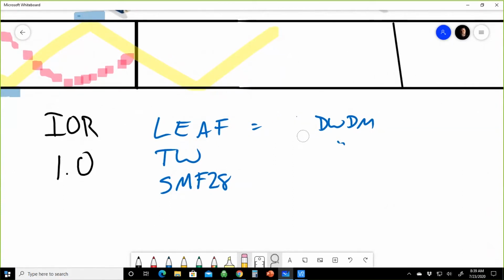So if you pull up the white paper specs on these, it'll have that information in there. You can go to Corning.com, Prysmian.com, whatever company is making your fiber, and look that up, and it'll tell you the index of refraction. And plugging in that index of refraction, which I'll show you when we get to the OTDR setup portion, will help you do that precise fault isolation. And so again, index of refraction is the speed of light within the glass.